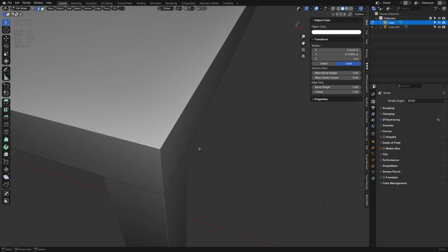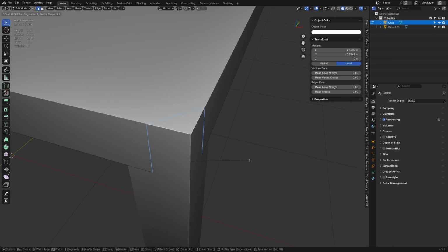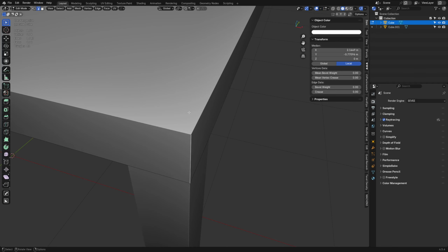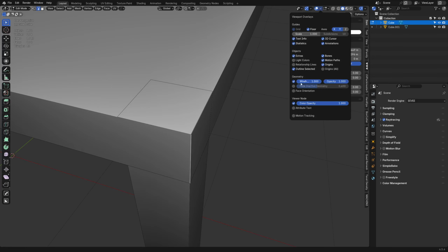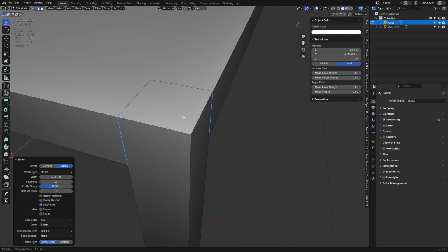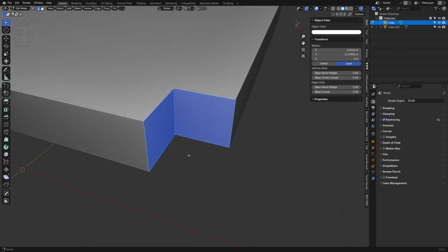We're going to do that over here again. We're going to start beveling. Also, you'll see me flicking on wireframe. I'm using a shortcut on my mouse for this. Okay. So wireframe on and off up there. You can right click that little checkbox and assign it to a shortcut if you want. All right. But if I Control B and I bevel and I mouse wheel up now, we get that little curve happening there. But we can change the profile shape and we can send it back the other way like this. So if I hit slash and isolate, we'll see this number here.